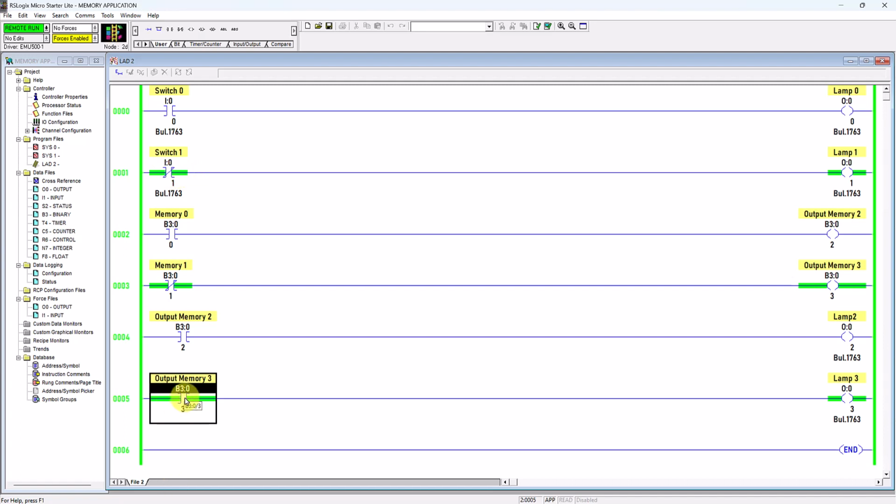Because it is triggered from normally open to closed, the virtual power can flow through this rung and then energize this virtual output coil. Thus it will turn on the lamp 3. So what happened is if I trigger this to close, this lamp will be energized and turn on. If I trigger this by clicking the toggle bit, this virtual switch will trigger from normally closed to open, hence no virtual power to energize this lamp 1. Hence this lamp 1 will be turned off.